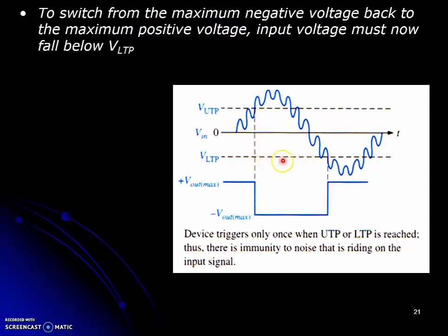And this change is the key point about how the noise effect can be reduced. Now, the triggering point is so low, it is impossible for the input signal to cross over the triggering point, so no further triggering occurs, and the output stays low so long as the V negative is higher than the V positive. When the input signal goes lower than the lower triggering point, the V positive becomes higher than the V negative and causes the output to switch from low to high.